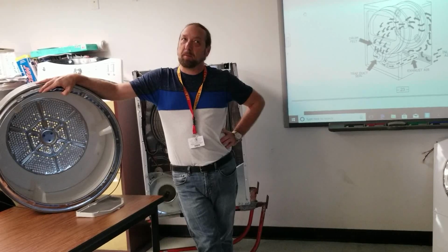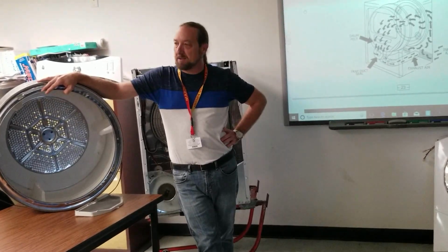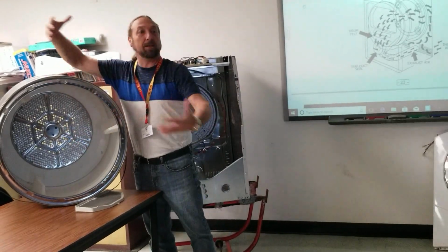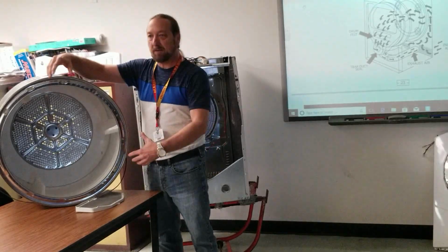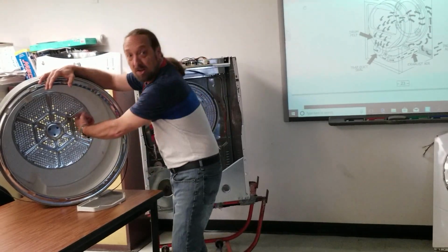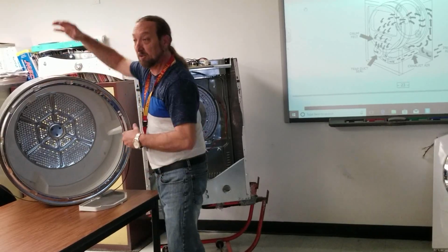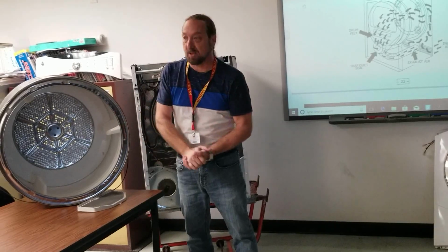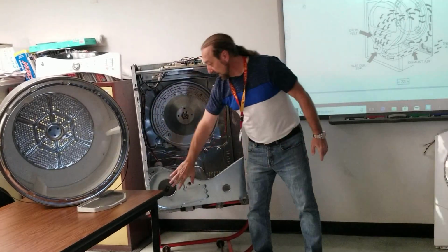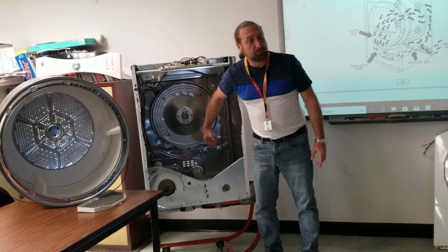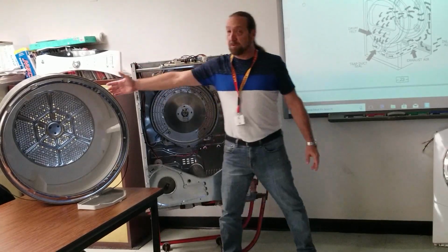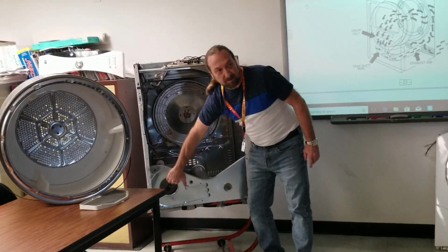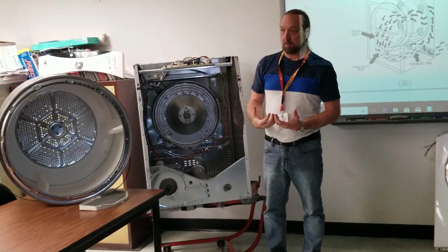Well, no, but what I mean by positive, negative airflow is, if it was positive airflow, that means the fan would be blowing air into it, putting it under pressure. Negative airflow is like a vacuum cleaner. It sucks the air out of the drum. It's pulling air from the back side, but instead of blowing into the drum, it's sucking out. And in this case, this fan is here, the heater's in the back, so air flows out of the heater, goes in through the holes in the back of the drum, over the clothes, and it gets sucked here, so we're in a negative airflow.